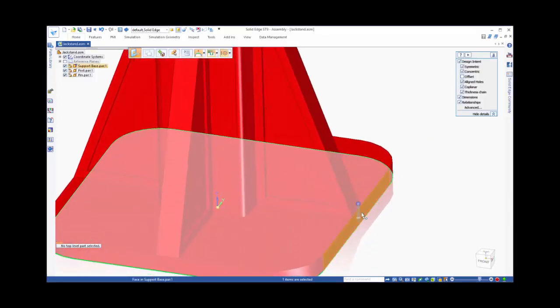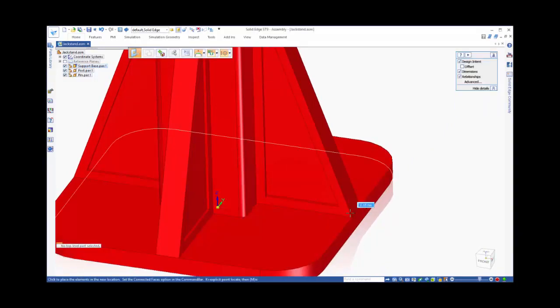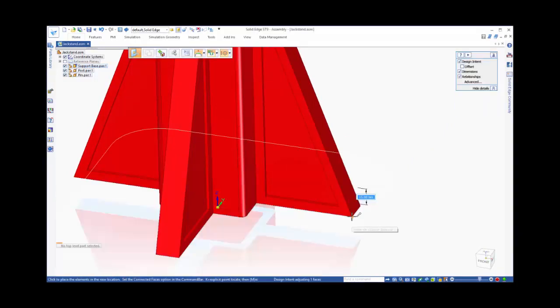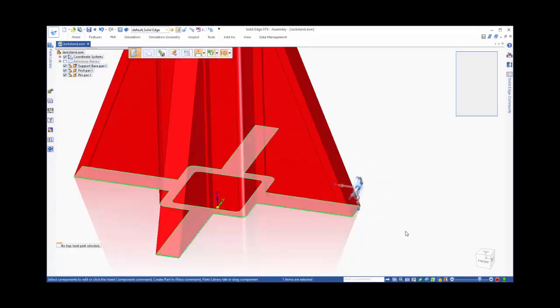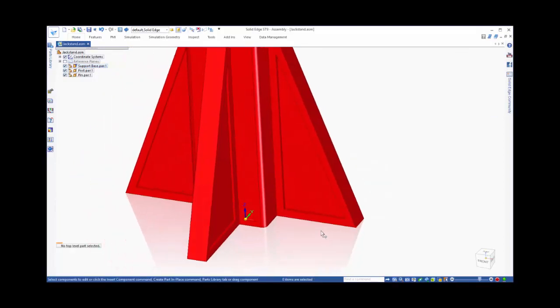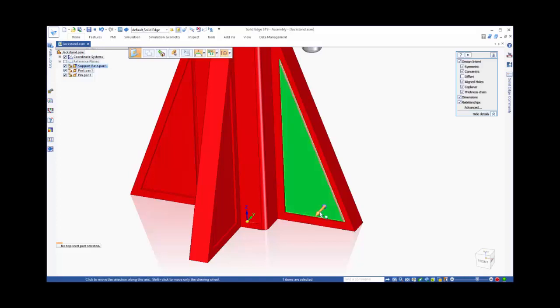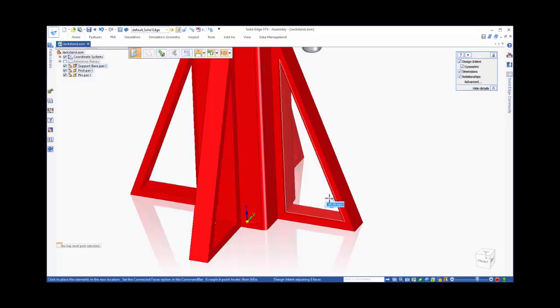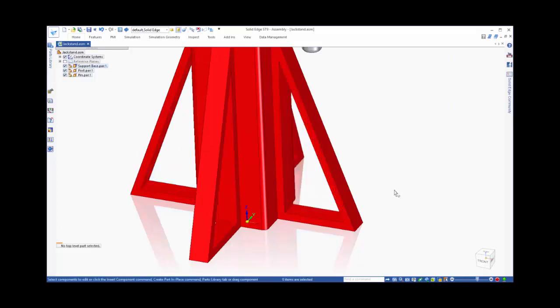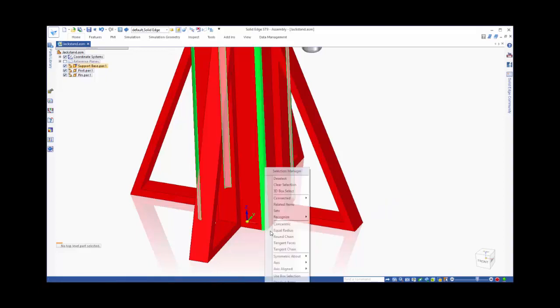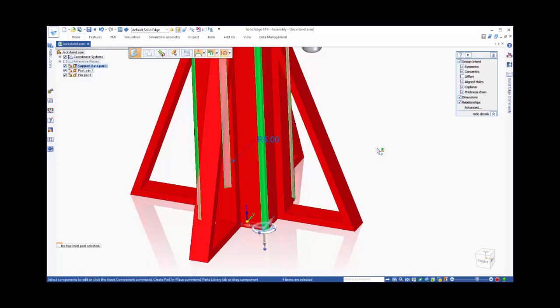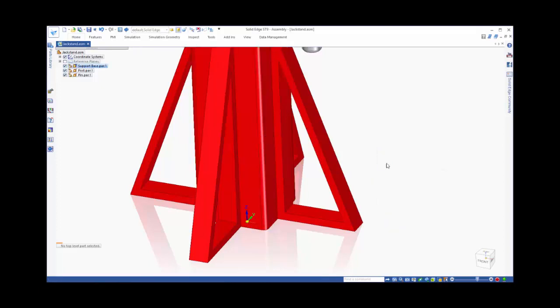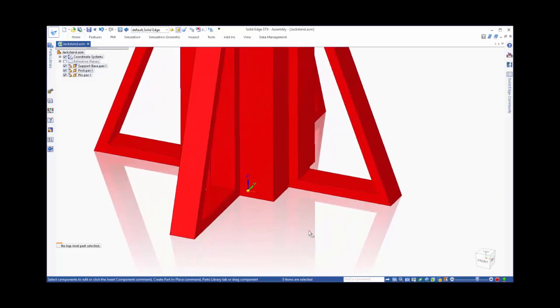By disabling the offset design intent, we can remove the bottom plate by simply dragging the bottom face up to the point where it disappears. We can use this same technique to remove the recessed area of the angled ribs. The Selection Manager tool enables us to interrogate the model automatically to detect and find all the rounded corners that contain the same radius, and in this case we'll use the selection to remove these rounds.